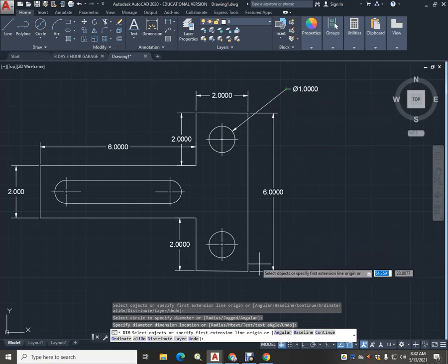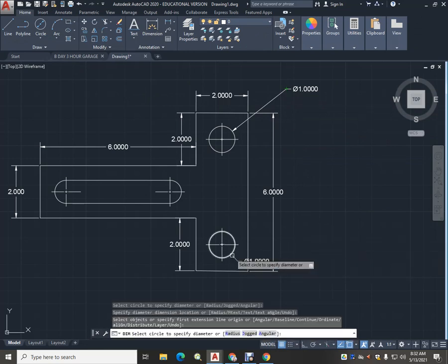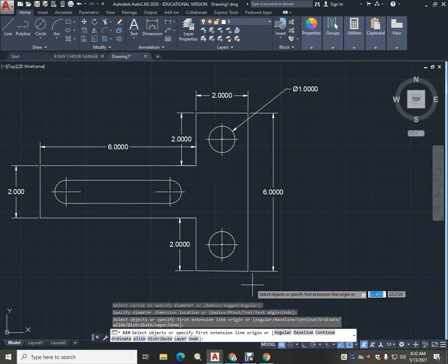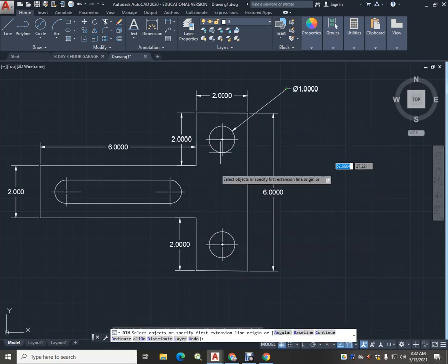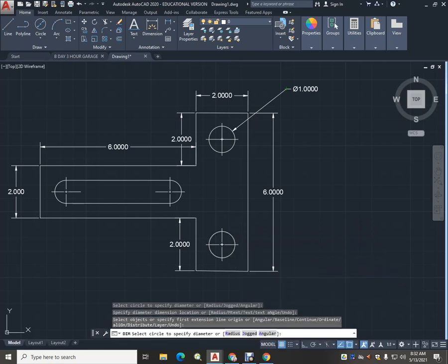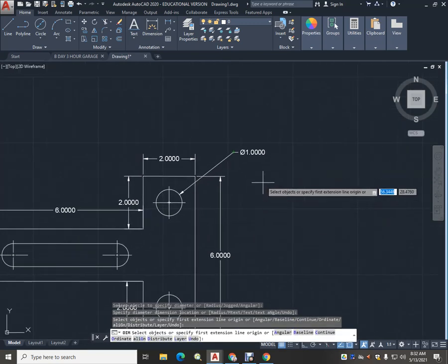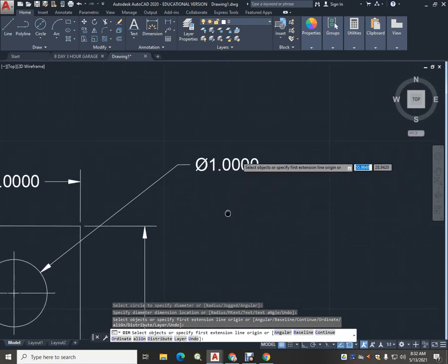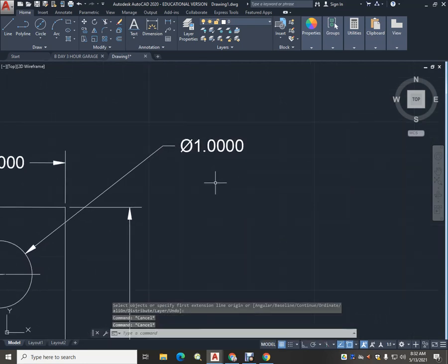Okay, so here's a little secret that I learned in the war. If you have two circles that are exactly the same kind, rather than dimensioning both of them, which we certainly could, there's another little way that is acceptable, and that is we just tell the reader how many circles of this size that we have.